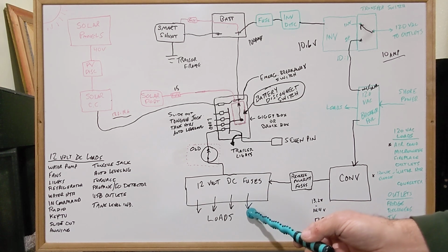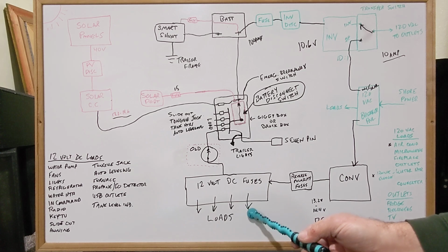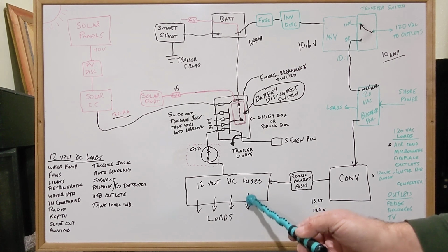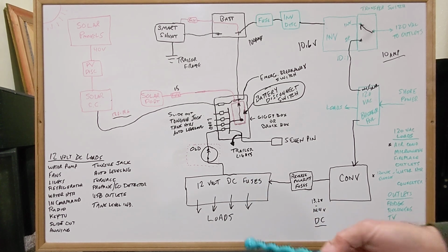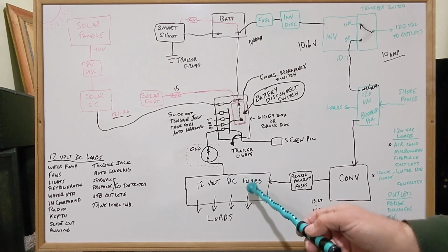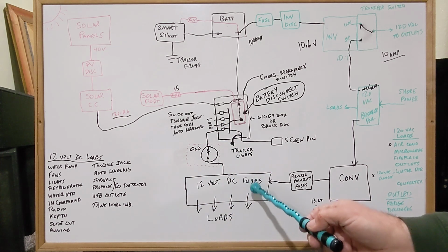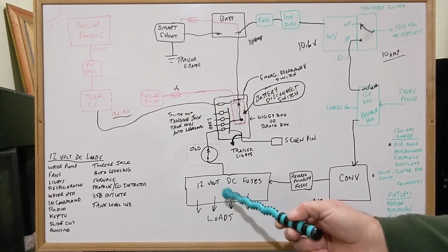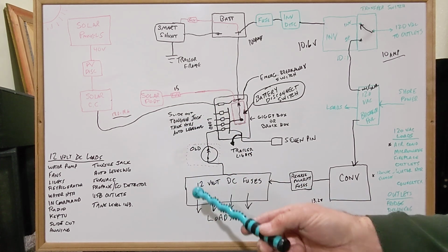That only works if you have a load attached to that fuse that's turned on trying to run. If there's something attached to it that's not turned on, like a light where there's no load, that blown fuse indication won't come on, but the fuse could be blown. So if you see a red light in the fuse panel, that means you've got a blown fuse, but it doesn't necessarily mean you'll see a red light for every blown fuse. If that's not confusing, sorry.